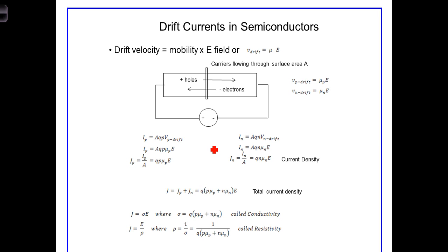But at the very beginning of our study of electrical engineering, we noted that traditional current flow, I, refers to the flow of positive charged particles flowing from a higher voltage to a lower voltage, even though we now know that the positive charged particles are bound in the nucleus, and in fact that it's the electrons flowing from lower voltage to higher voltage. But back before, it didn't matter, because at the device level we couldn't discern the difference between a positive charge flowing in one direction and a negative charge flowing in the opposite direction.